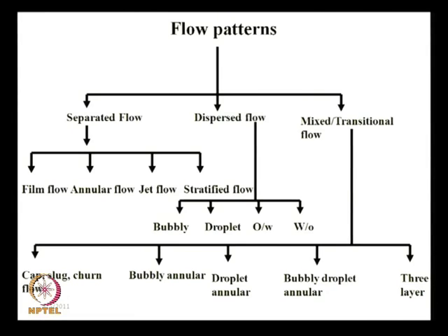When we have separated flow, it is very easy to model them. We can just consider them as two separate fluids. When it is completely mixed flow or completely dispersed flow or a homogeneous flow, again it is very easy. We can consider it as a single fluid with suitable average properties, is not it? The entire thing is mixed. So, therefore, the properties are uniform throughout in its cross section, along the length, the fluid properties are uniform throughout.